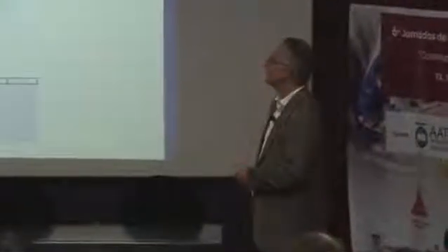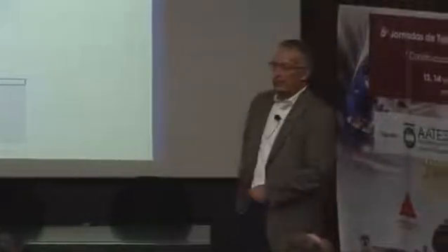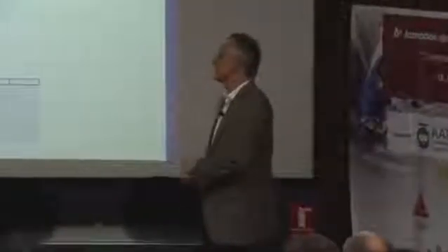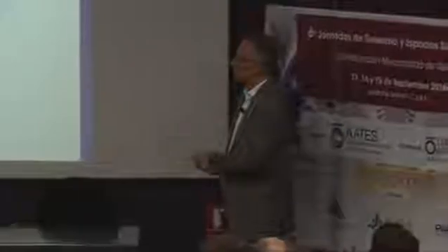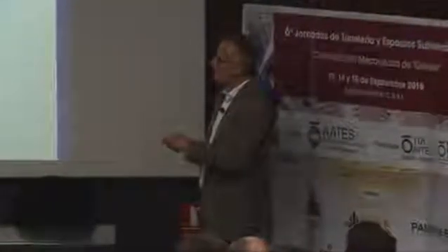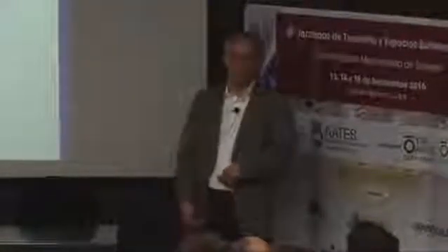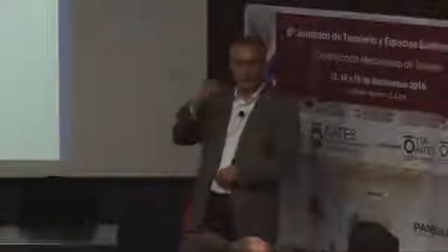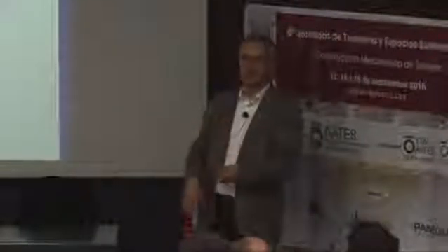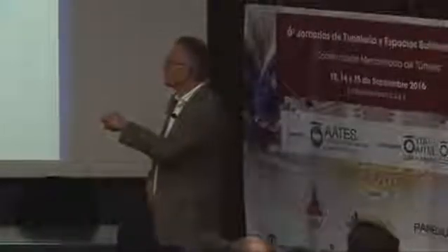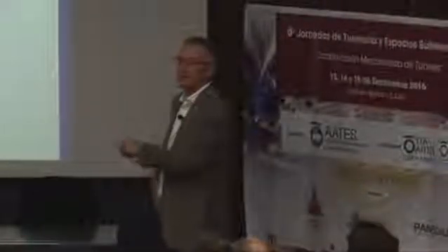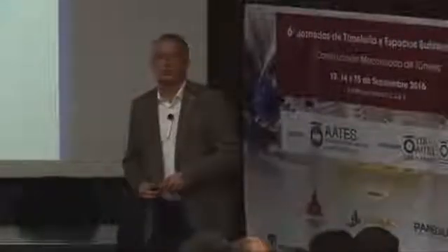So here again, the picture which I showed before: filter cake for face support pressure application. We have, of course, another effect in active face support tunneling, and that is the time dependency. I mentioned before, with a slurry TBM, the membrane is scratched off by the rotation of the tools every turn, and it has to rebuild by itself. So you have, at the end, quite a good definition of the size of your membrane during the operation of the TBM.